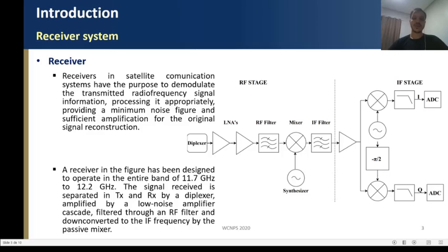There is a trade-off between linearity, low noise figure, spectral efficiency, high gain, and low power consumption. To balance these trade-offs, a heterodyne receiver with double demodulation was designed, adding an IF frequency before the baseband signal.